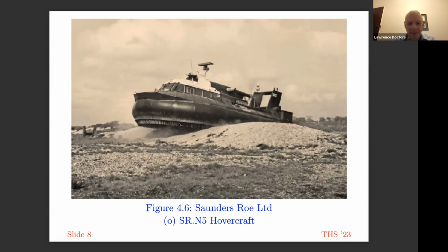In later air cushion vehicles, the fingers, of course, have grown to about 1/2 of the total depth of the skirt. A rule of thumb that seemed to be used in the early days was that the height of the skirt that could be maintained was something like a quarter of the beam of the hovercraft. Anything much more than that would mean that you'd have problems with lateral stability.